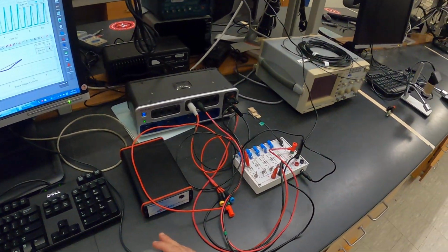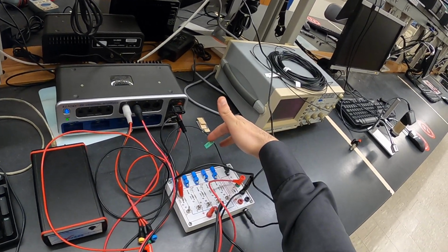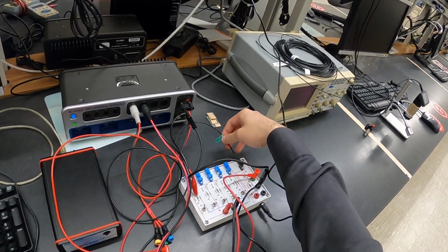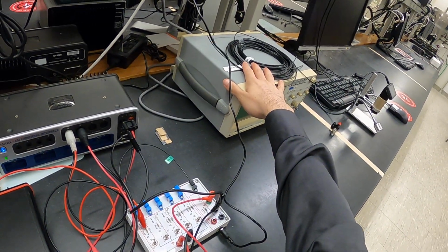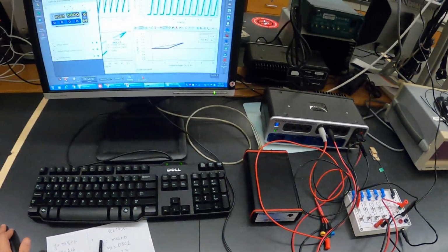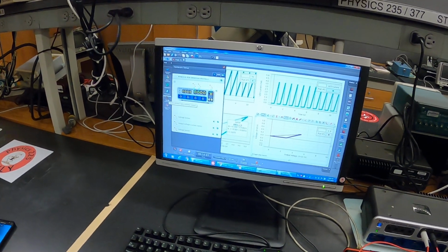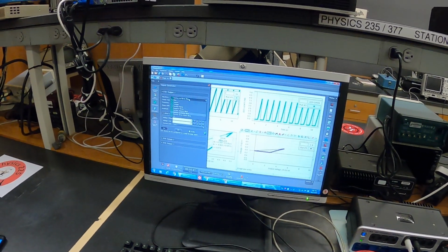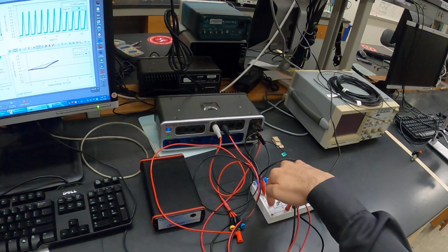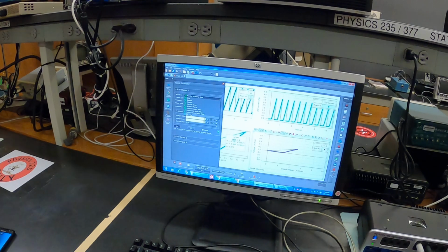So in the second experiment, you will change the fibers. First we'll measure with a 30 centimeters fiber, and you want to compare the transmission for each different fiber. In order to do that, now you have to send a DC signal. So you keep the same voltage on this LED and all LED. So you keep the same voltage.